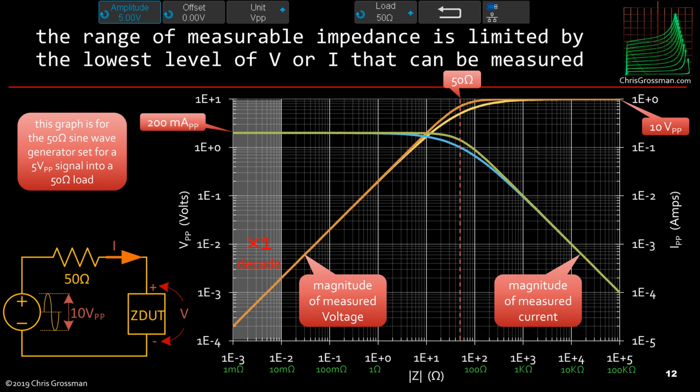So now let's think more about what we're doing with the measurement. Current probes like lots of current. They don't like measuring tiny currents. So to get lots of current, we basically turn the function generator up as high as we can. This is the way I set up the function generator in the Bode plot on the scope.